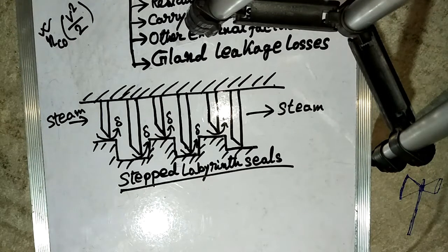The leakage of steam occurs between the stages and also at the shaft, and the inlet and exit ends of the casing. The diaphragm leakage takes place in both impulse and reaction stages through the radial clearance between the stationary nozzle diaphragm and the shaft or drum. The tip leakage occurs in the reaction stages through the clearance between the outer periphery of the moving blades and the casing because of the pressure difference existing across the blades.